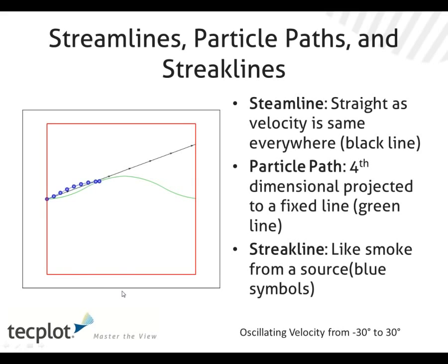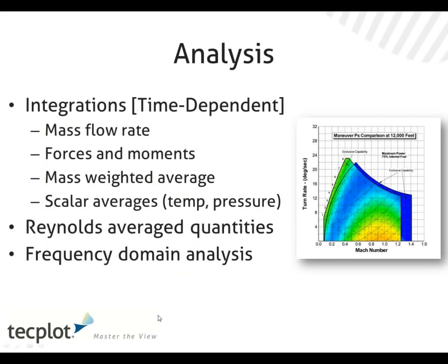The streamline in this case may not be very meaningful to you because it just is going up and down. And you'll see this in some of our other animations as well, where the streamline really jumps around a lot. But the streakline and particle path, either one gives you a good idea of what's actually going on in the flow field. Now, if we extend this to the analysis world, we've talked about streak lines, streamlines. When we do quantitative analysis of time-resolved solutions, we really need to look at the integrations in a little more detail in terms of mass flow rate, forces and moments, and we'll talk about that in the subsequent slides.